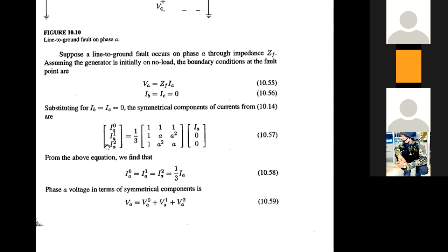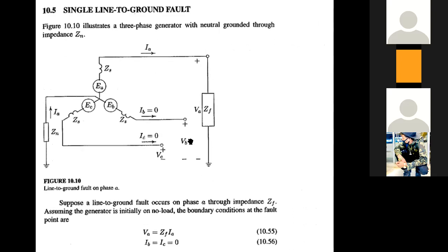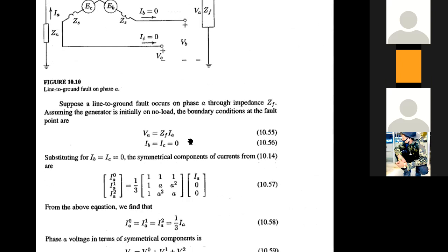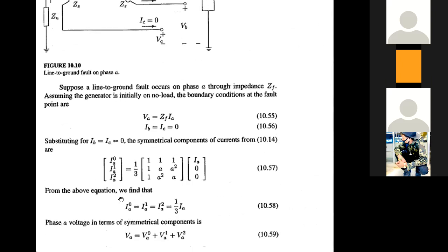Here you can see when we put the single line to ground fault, that was discussed in the last class. It is the matrix outcome, right? The simple multiplication will generate this expression, the single line to ground fault expression, when we have only IA present. Which type of fault is this one? If we just check this matrix, can we identify which type of fault this should be?